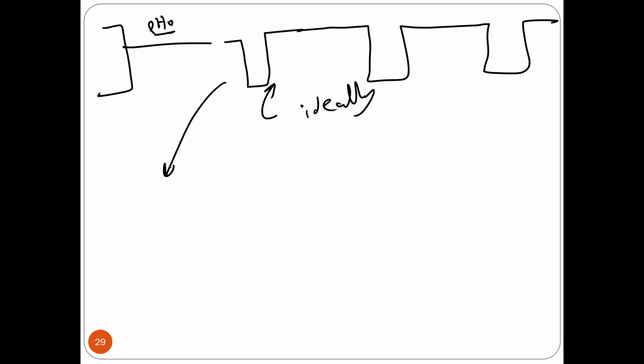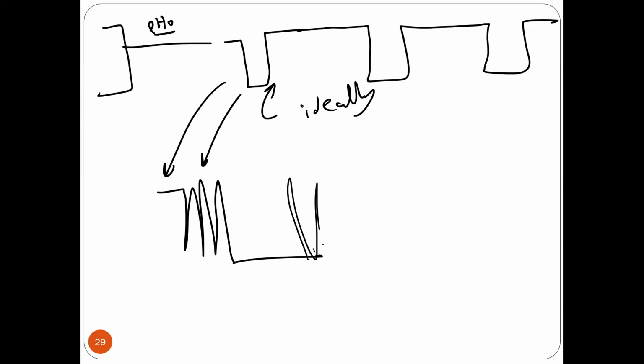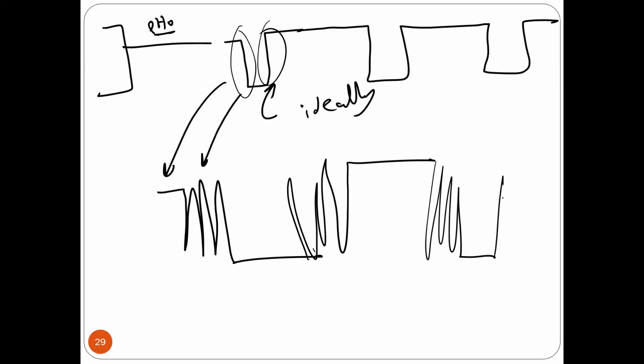signal I'm going to get. What I'm going to get is a bouncing this way before it becomes 0, here at this part, and then bouncing before it becomes 1. So it's not going to be this way. There should be some bouncing, bouncing 0, bouncing 1. This bouncing, I think it is around 5 to 10 milliseconds. It's going to bounce for 5, 10 milliseconds.